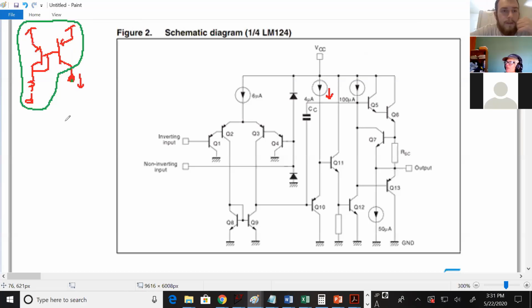Is there a way to increase it even more over a cascode? Are you asking to add on to our cascode or something completely different? It's the homework flavor number 4. Gain boost? Gain boost. Yeah, so you could gain boost it if you really wanted a good current source. Okay, so all of those are ways to make this look like a big resistor.